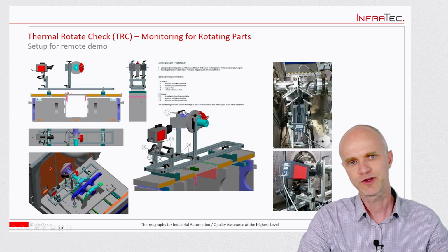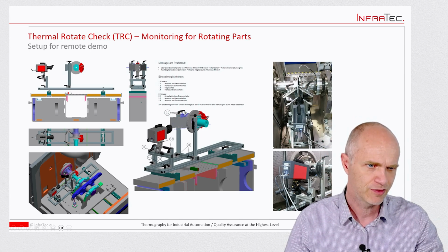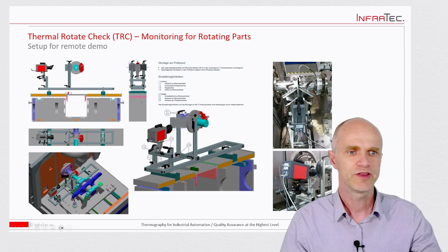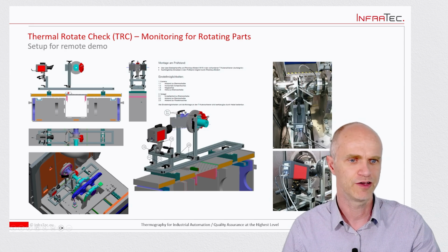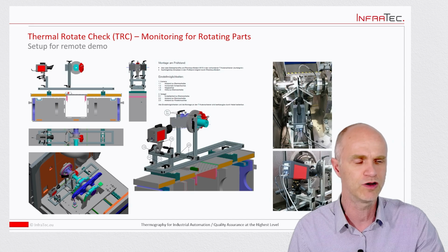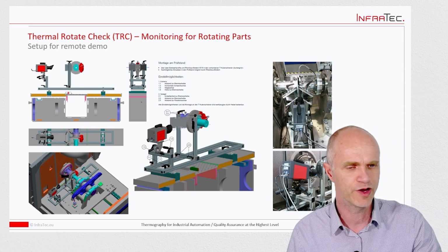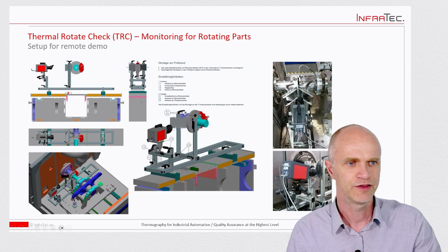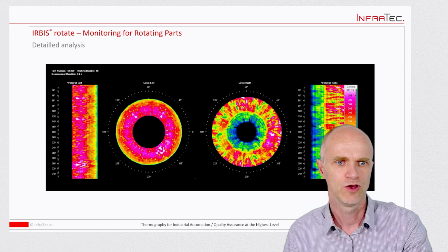And so it's possible to detect with one camera and using a line scan, going from left side to the right side, directly to detect both sides of the brake disc in one view, and this at a very high speed. So it can be measured up to 300, 400 kilometers per hour. It can be used for motor brakes, car brakes, and train brakes. So for different diameters. And yeah, it's possible to see any inhomogeneity on the parts.